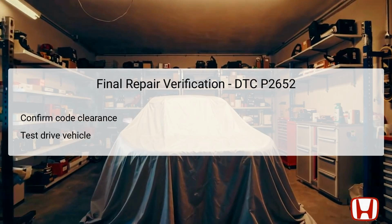After completing all necessary repairs for DTC P2652, it is vital to perform a final verification to ensure the effectiveness of the repairs. Start by clearing any remaining trouble codes using the Honda Diagnostics System, HDS, once again, confirming that the DTC no longer appears on the diagnostic interface.